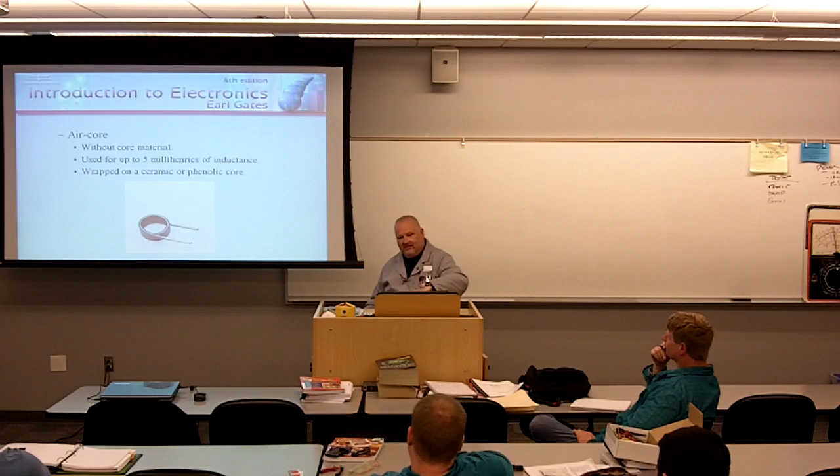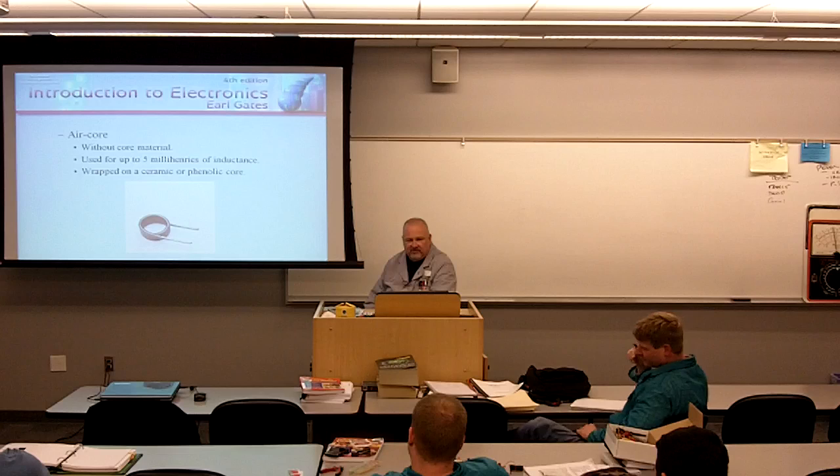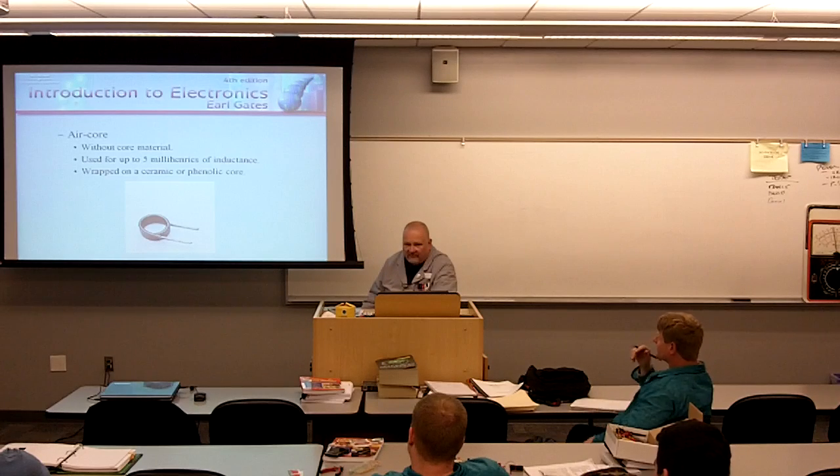You dip it in paint thinner, paint remover, and it removes that right down to the metal, and it makes it solderable. You have to put a neutralizing agent on it, but that's the best way of doing it. Other than that, your wire strippers are just basically going to scratch the stuff off. It's not really going to work, because this is a lacquer coating on it.